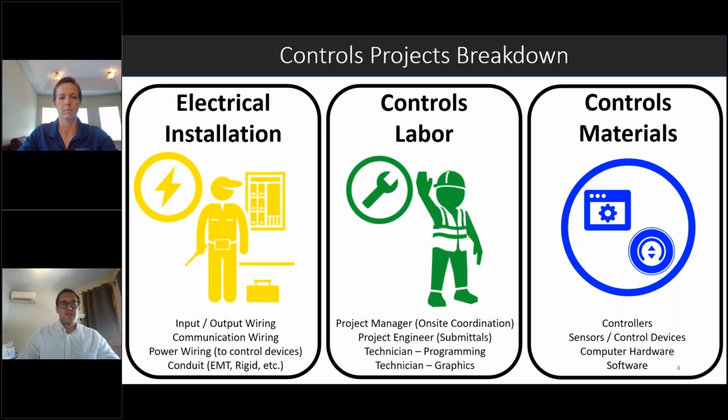BAS manufacturers sometimes need to be powering up their panels for their controllers, their controls. And you need to consider with that the different types of wiring requirements that you have. So when wiring in mechanical rooms, you would probably want to put that in conduit to protect that wiring. Also outdoor wiring, you'd look at rigid galvanized steel as a type of conduit that you'd use outside to protect your wiring so that it's not getting damaged by everything outside.